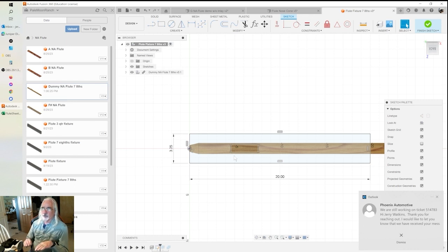So now all I have to do is tell it to go to work zero, and then I tell it that it's actually -1. So I set my X to -1, and then tell it to go to work zero again, and it should go over exactly 1 inch and be lined up perfectly to cut this. Because of this tapered end, it's a little difficult to set your XY with your probe tool, if that makes sense.